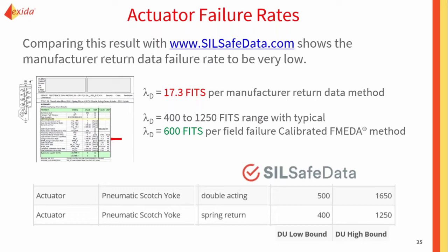It is on the lower side, but this might not have as many O-rings, or it might not be as complicated. There might not be as many ways to leak or have dangerous failures or bind. And I'm not sure what the environment is, if this is open on trip or close on trip. All of that can play a part in this. However, when I get something that's way, way below what is typically seen in industry, I'm not saying reject it. I'm saying let's start asking a lot of questions.